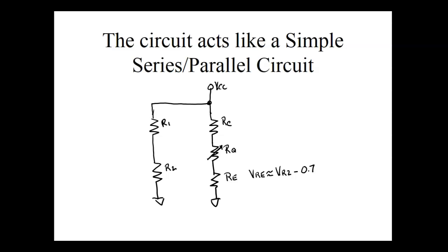How many of y'all can solve this circuit right here? Where did you learn how to do this? DC. Of course, you can't solve it now because I haven't given you any values, right? So this is the equivalent circuit for voltage divider bias. Basically, this is the transistor right here, and I'm controlling the transistor with this voltage right here.